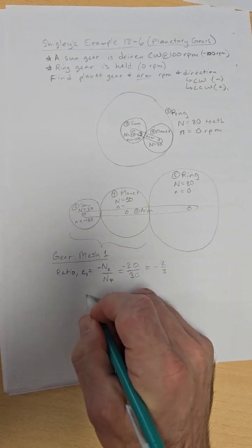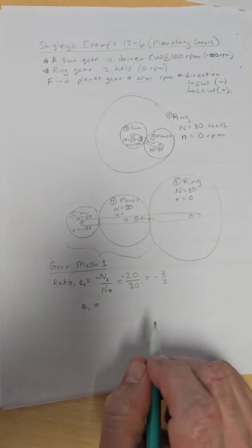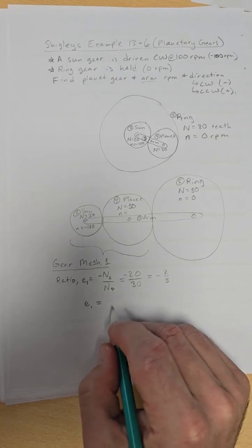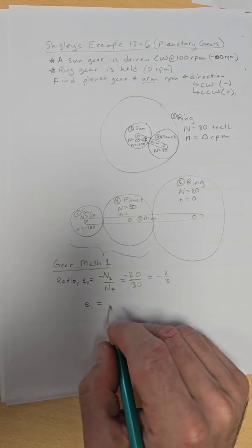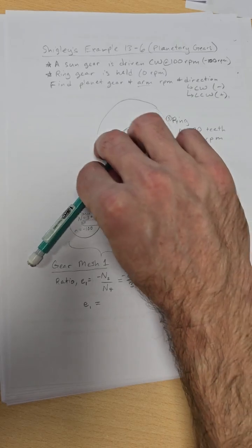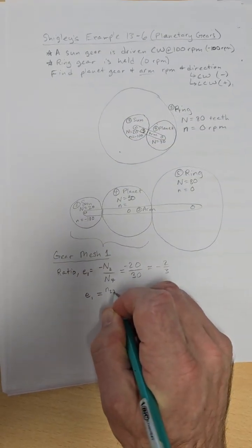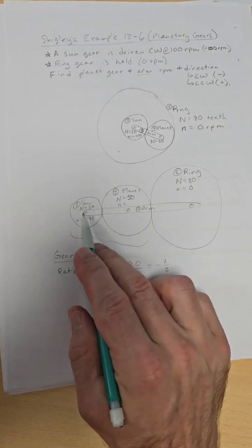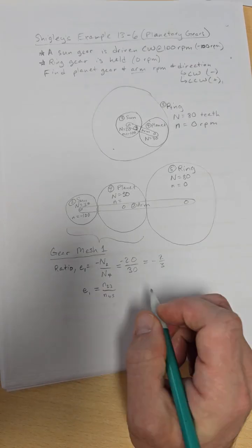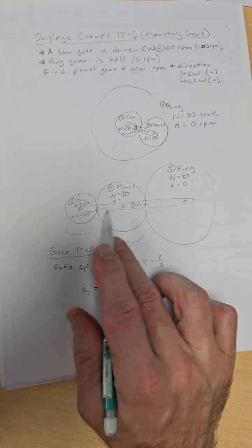Now, with the law of gearing, we also know that the ratio of teeth is inversely proportional to the ratio of the speeds. The planet has to have the speed of the arm subtracted from it. So we define N2,3, which is the speed of 2 relative to 3, and N4,3, which is the speed of 4 relative to 3.